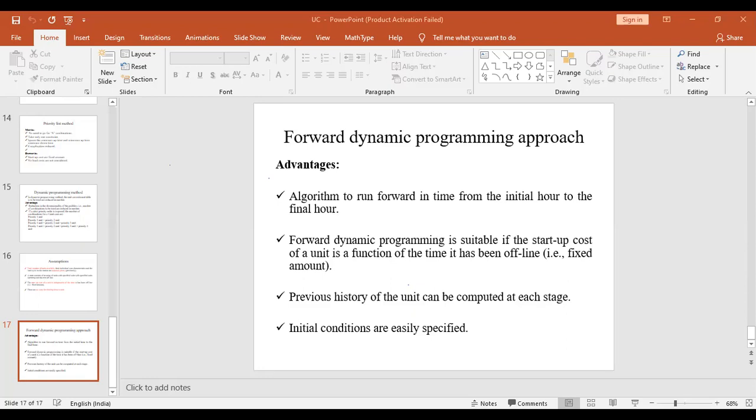This lambda is the Lagrangian multiplier. Pn, the power generated across the nth unit, can be calculated by means of Bmn. Bmn are the loss coefficient values, and lambda is the Lagrangian multiplier. This is the entire function for calculating the fuel cost of each unit connected to the power system. If the number of units increases, the amount of loss will be reduced, and the operating cost increases, which results in the minimum fuel cost of the system.